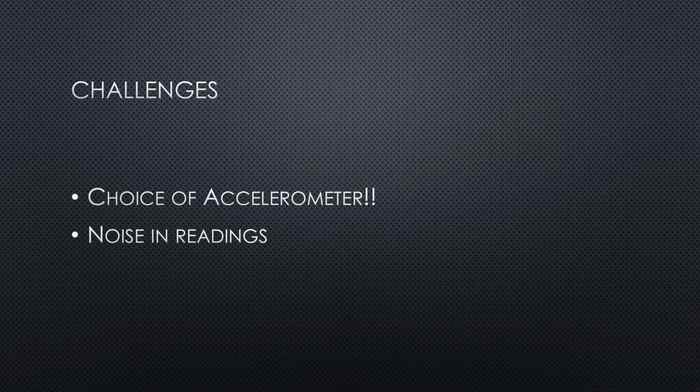As mentioned before, a mistake was made in choosing the accelerometer initially, and finally the MPU 6050 was chosen. Noise also created a problem, which was compensated by taking the difference of the spectrum that removed most of the noise, and then some filters were applied to remove the white noise that was observed in the signals.